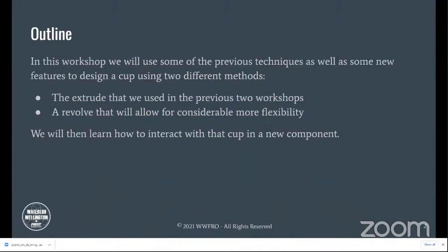Today's session is going to build on the sessions we've had already. So we'll use some of the techniques that we did in the past, and we'll start to learn some of the more advanced features as part of xDesign. And this time we're going to start by making a cup in two different methods. The easiest way, the quickest way is to use an extrude that we've done in the previous workshops. And it's a little bit limited that way, and a more flexible way is using the Revolve feature that we'll go into. And once we have our cup made, we'll learn how to interact with the cup in a